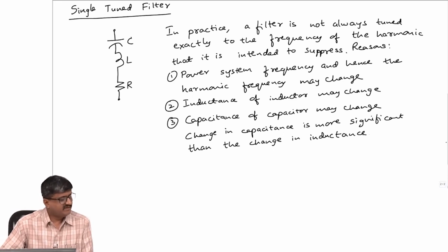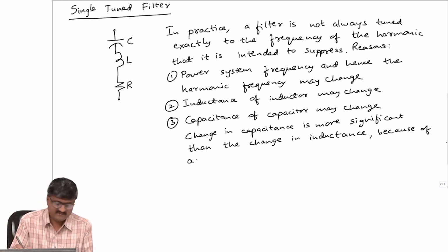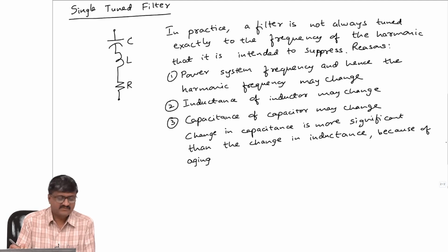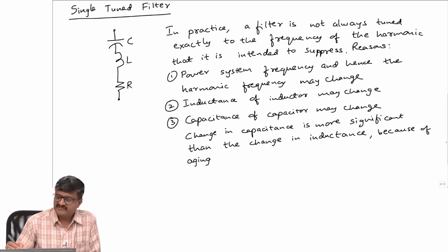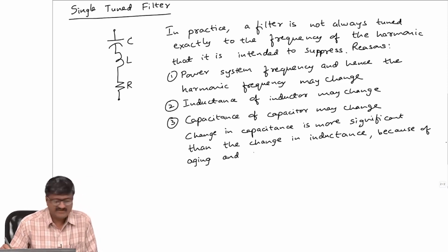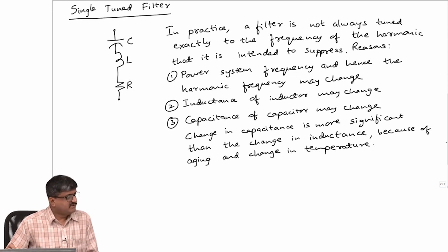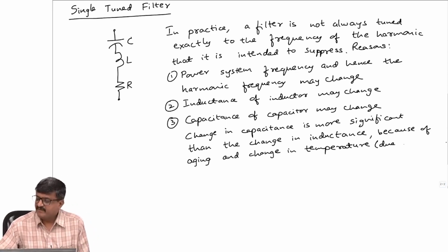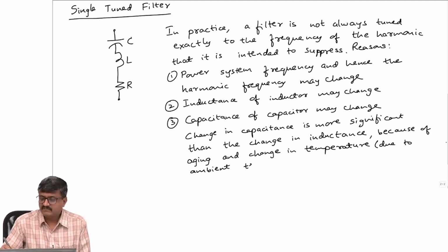This is actually because of aging, which means as you keep on using the capacitor for more and more time, as years pass by, it ages. So, the capacitance itself will change, and also change in temperature, which can be either due to ambient temperature or self heating.